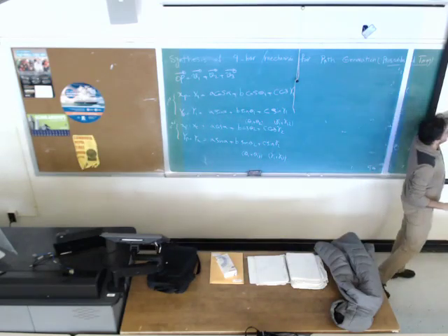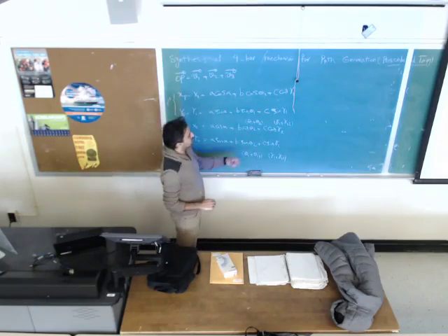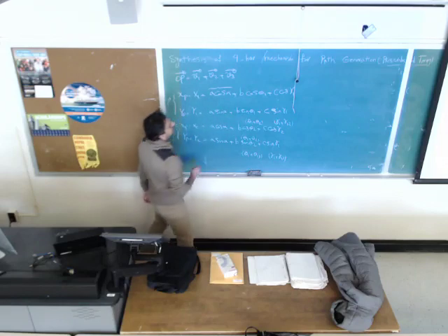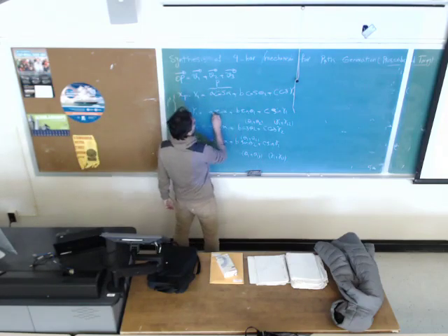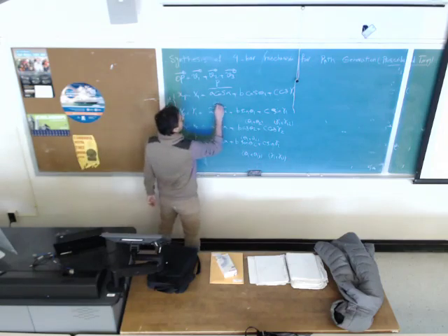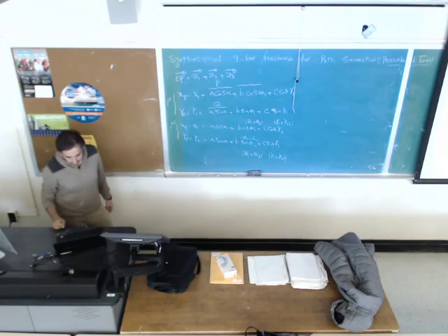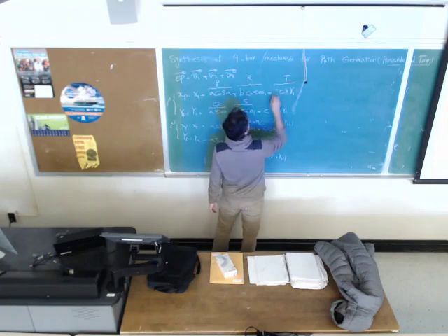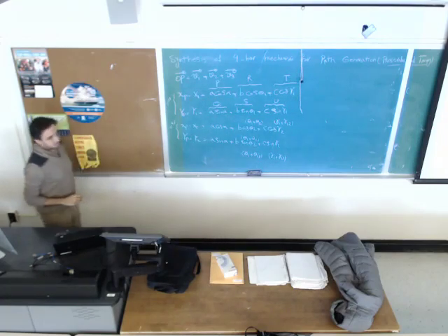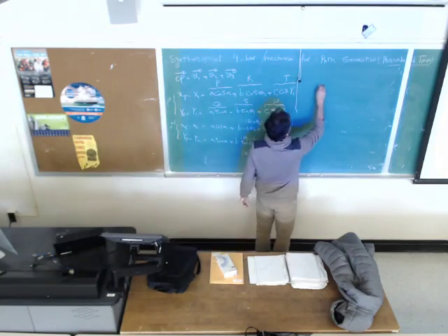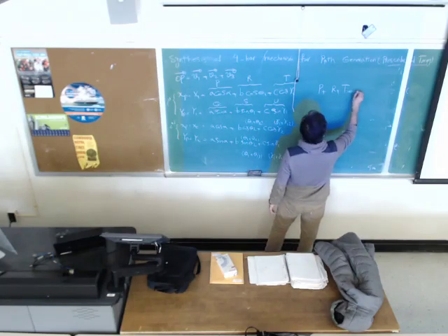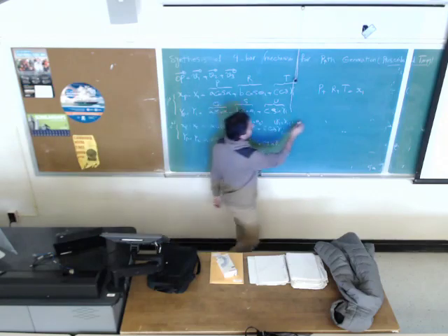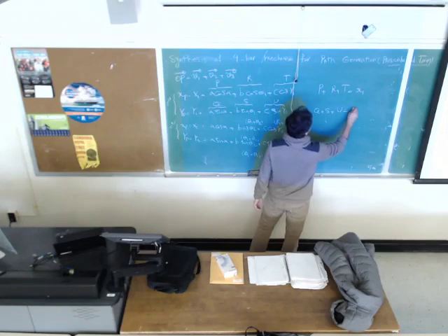I'm going to rewrite the equation in this form, and then I expand them, similar to the motion generation. If I expand this, you know how to expand the cosine and sine terms. Then I define some intermediate variables. A cosine of alpha is P, A sine of alpha is Q, B cosine of theta 1 is R, S, T, and U. So first equation is going to be P plus R plus T equals x1. x1 is the coordinate that we would like to have point P at first position. Q plus S plus T plus U would be y1.